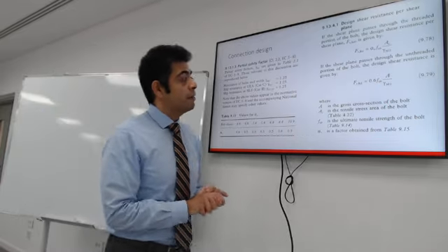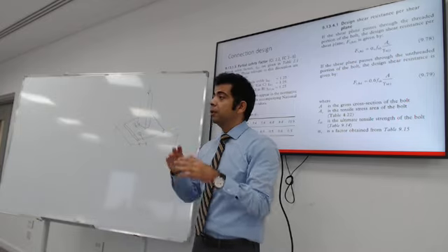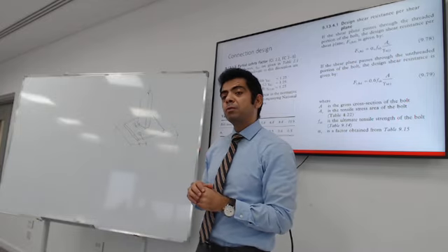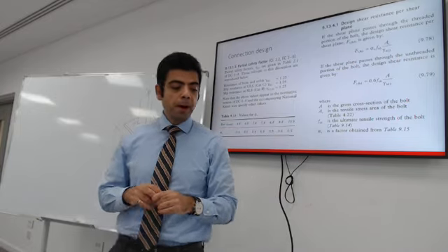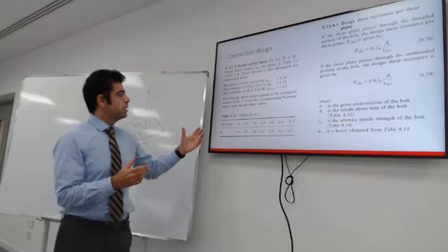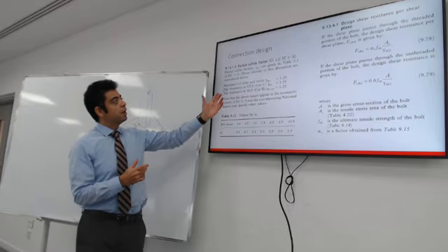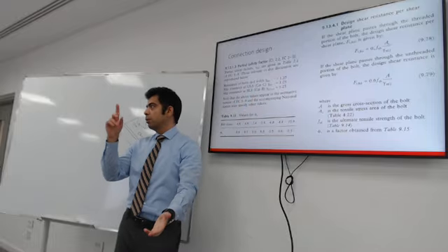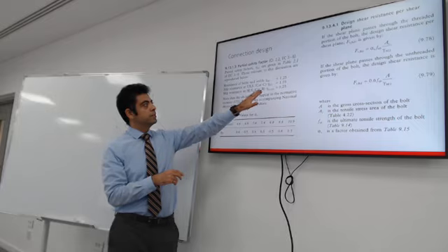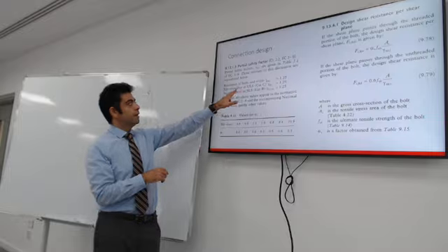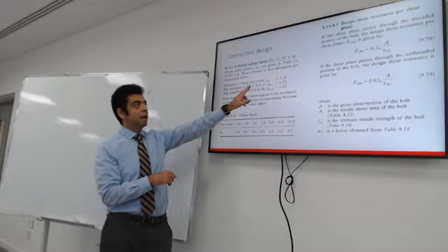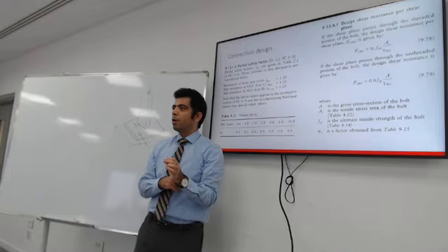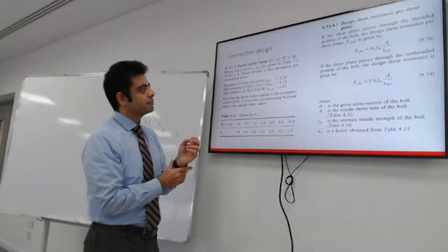I think we'll have a better chance to go through the application of the equations when we take an example. But long story short, the code is trying to tell us the safety factors. Remember the gamma 0, gamma 1 and gamma 2? When you're designing a bolt or a connection, it's not 1 anymore, it's 1.25.